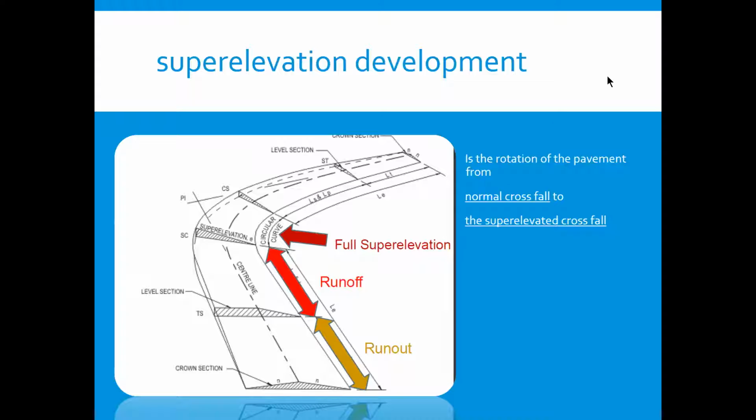On divided major urban road, the cross-section may be rotated about one edge of each pavement. In both cases, the presence of public utility services, the necessity to provide access to the abutting properties and intersections, and the necessity to match with levels at the right-of-way boundary may require the use of some other points of rotation. A profile of typical superelevation development is shown on the slide.